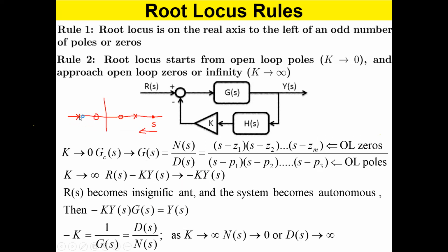So therefore, I can draw a thick line here saying that I'm satisfying the root locus phase condition. So this is part of the root locus here and here, right? So there you can see two parts. This part and this part is on the root locus, RL. So this way I can actually mark sections of the root locus on the real axis. Okay, so that is something really important to know, and that is what is called rule 1.